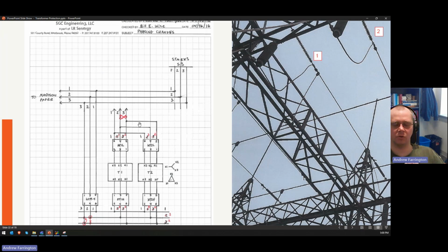And I said, well, that's great. We can just close that switch and then open these breakers and take your transformers out of service and do our changes, and then we can close everything back in, open the switch back up and switch back over to the municipality's power. And they said, no, that we can't use that switch because it doesn't phase.